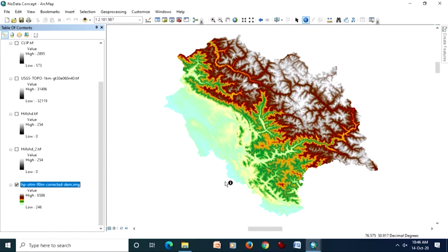The rest of the areas are mixing with the ground, that means the no data value. So whenever you encounter such problems, try to handle these things through no data. And as I have already told you, once the no data has been declared, that value is never used in any kind of calculation or estimation or statistics. So that value is always ignored by the software.